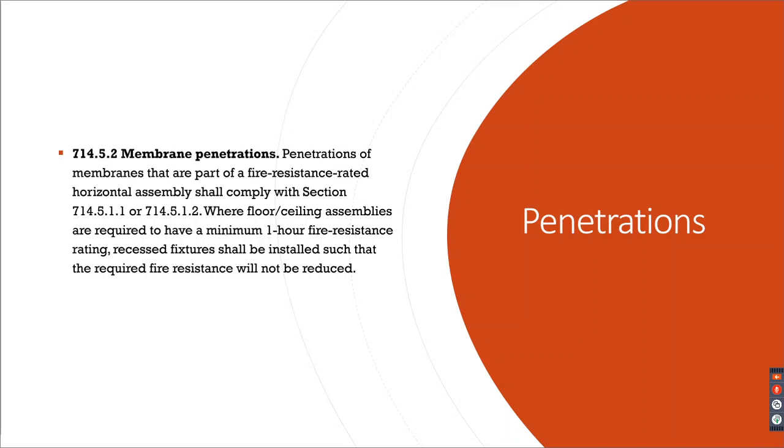So we see that a lot in many places. For example, if you're in a 5A and you've got a ceiling roof assembly and that ceiling portion is rated, but again, like I mentioned earlier, it's not the whole assembly, right? That's just one portion of the assembly. The rest of it includes the roof portion, but you've got light fixtures popping up in between, up in that ceiling assembly. Those have to be protected. Yes, you've got to maintain that rating. So they're protected or they're listed and tested as part of this assembly.